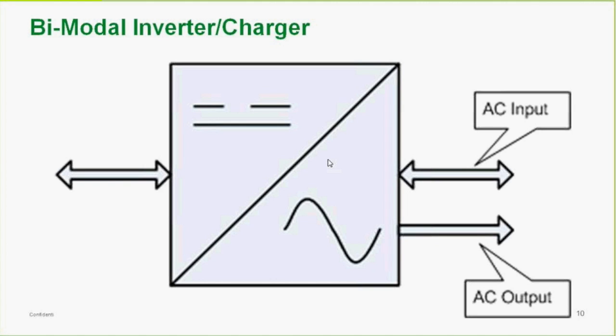The CSW, or Connect SW inverter, a smaller, less featured device, with some really cool features in its own right, cannot do bimodal operation. So you cannot do battery backup grid tie from a DC source, which we'll talk about in more detail.